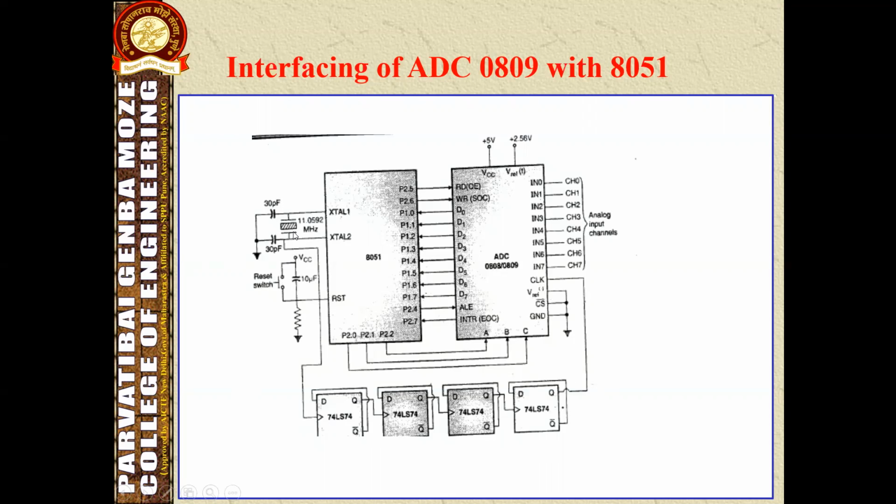D flip-flops are used to reduce and synchronize the frequency provided from the 8051, and after that the frequency is applied to the analog to digital converter. So this is the interface connection showing how to interface the analog to digital converter with the 8051.